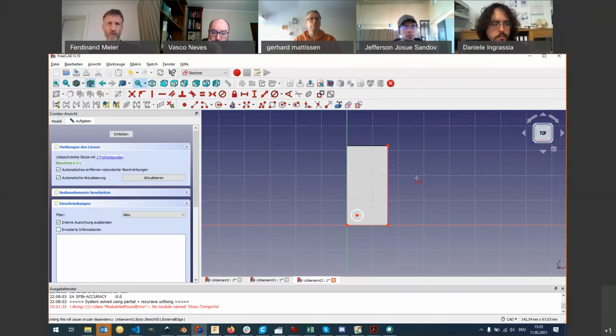Sometimes you don't want external references. Many times you have to. But at least FreeCAD keeps it very clear what is external and what not. So if they break, you know, aha, it was an external reference and you can fix it. Whereas Fusion doesn't tell you anything. It just says it's broken.